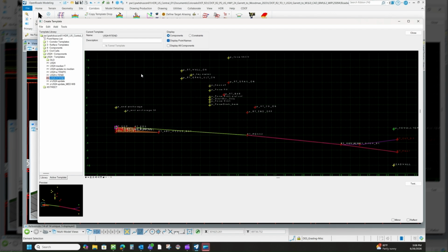If it's horizontal, or if it's vertical and the road is super elevated, it might occur on its own. So you have to be cognizant of super elevation when you're doing vertical controls. You also have to be cognizant of the switches when you're doing horizontal controls.